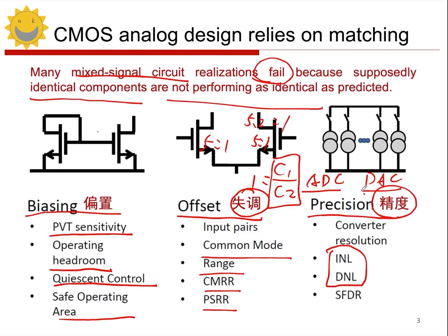For the DAC, there is a type called the current steering DAC. So what exactly is this so-called current steering DAC? It means that many current sources are arranged in a certain coding way, and then switches are used to control the flow of these currents to the same resistor. In this way, different current values flowing through such a resistor will generate different voltages on the resistor, thus completing a conversion from digital to analog. Here, the matching between currents will greatly affect the linearity of the DAC.